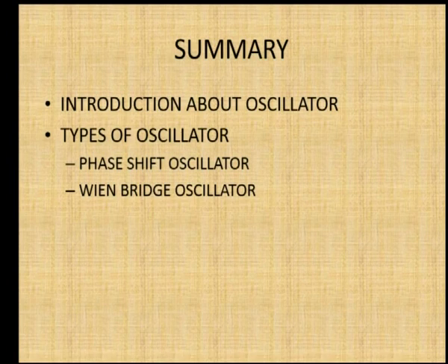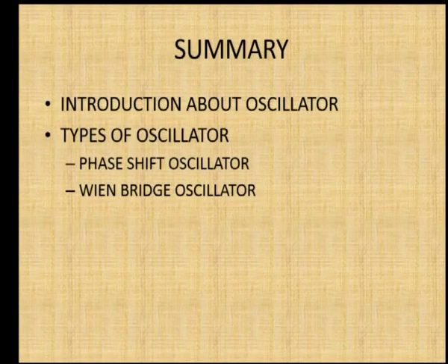So, if the output of the feedback network and the input are equal, then the oscillation will be generated as the cycles go on, and after that the external input signal will be removed and the circuit is closed, and as the number of cycles goes on, the oscillations will be generated and get saturated, and sustained oscillation will be obtained.